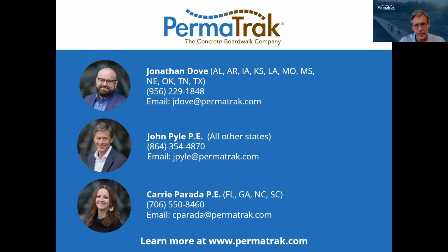One way to do that is to elevate the entire structure above the anticipated flood elevation. But again, you're adding a lot of cost, so it may not be feasible to design for that kind of flood surge wave action when you're on a beachfront like that. So that's a challenging environment.